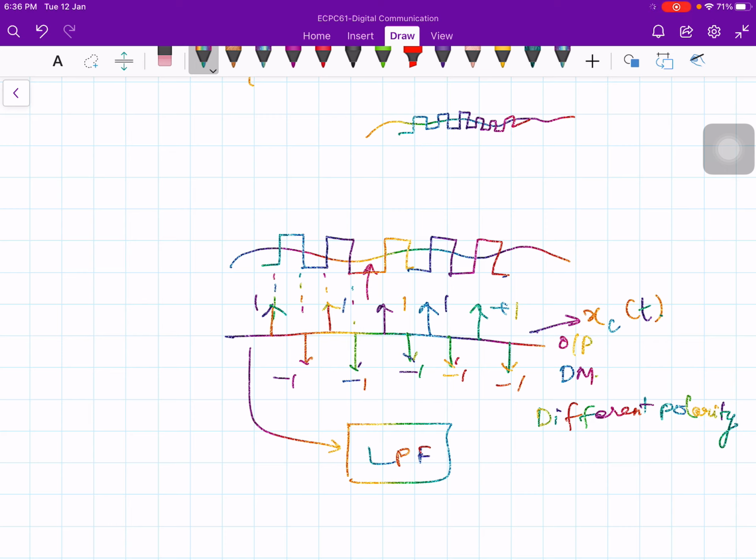So when we are undergoing a small variation, and if we have a large step size, this is what is likely to happen. And what we would like to do in this situation is reduce the step size, right? If it keeps on changing like that, then our motto is to reduce the step size. So when the delta modulator finds this situation happening, that is, alternate impulses are positive and negative, you can interpret it to mean that the existing step size is too large. Therefore, you must reduce it. So the step size is being controlled by the variable gain amplifier.